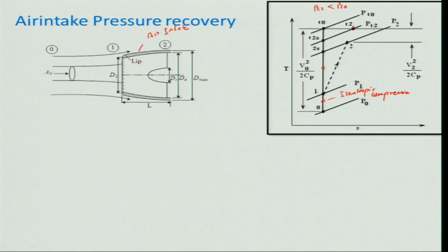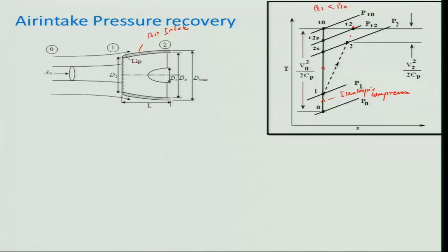Agreeable, disagreeable? It is not an isentropic process, whereas T2s, I am saying this is isentropic, s for isentropic, whereas the actual one is not isentropic. That means this dashed line is not isentropic. And the pressure P2 is the static pressure, that means there will be a change in compression, and I have indicated it in the dashed line.